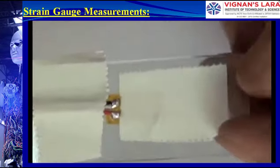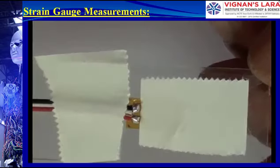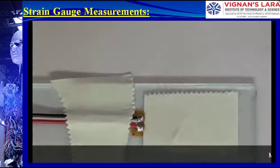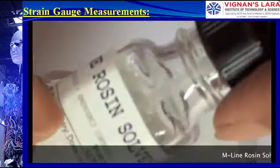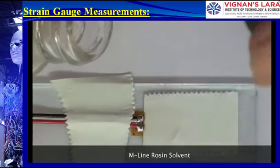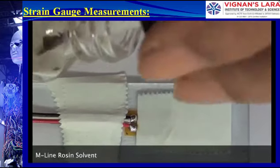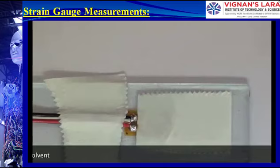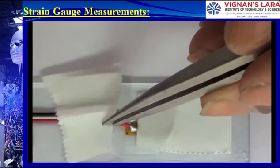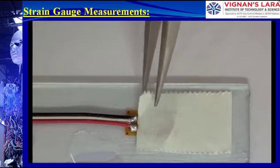The solder joints are inspected for proper connection, and if necessary they can be retouched with fresh solder. The PDT-2 tapes over the gauge and the wires are removed with a generous application of M-line rosin solvent, brushing the area a few times to dislodge the tape, which can be easily lifted away. The tapes should not be removed with any force to avoid damaging the soldered connections or the gauge.